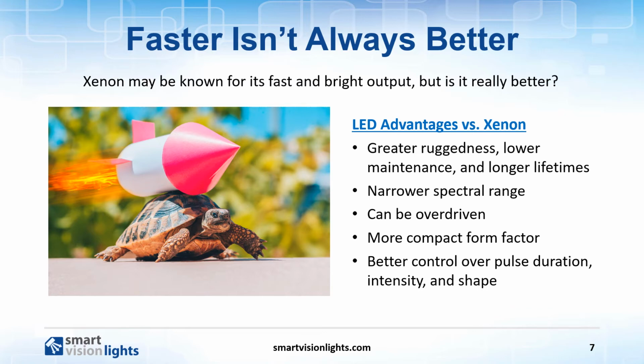As solid-state light sources, LEDs can be overdriven to provide higher intensities versus constant operation. This involves pulsing an LED at higher current for a brief period and switching it off for a specific rest time. As power increases, this provides diminishing return in output, however.